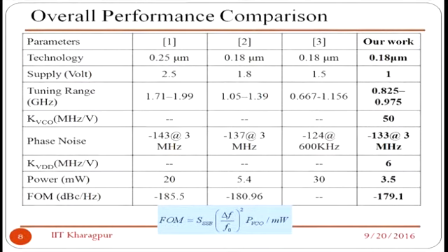And then in the literature, or any text, or in a patent, you will find various processes and various parameters. But how would you benchmark your VCO design against others? It is better if you define a figure of merit, which involves the signal strength, or the swing at a single sideband.